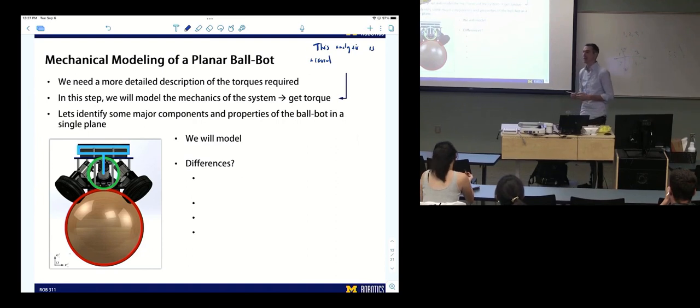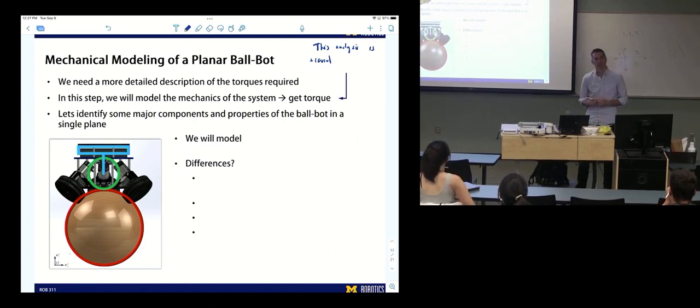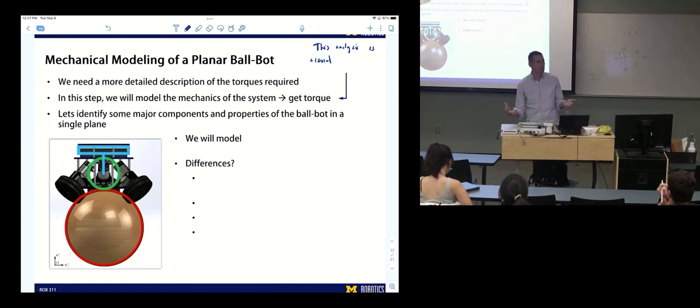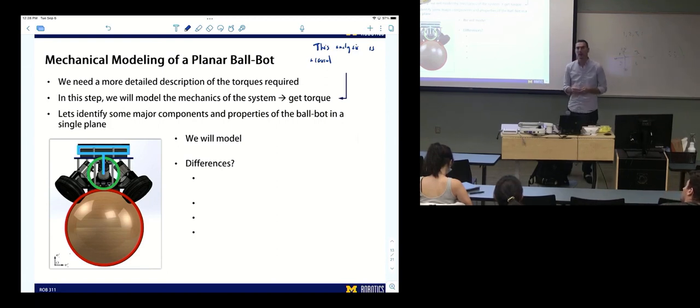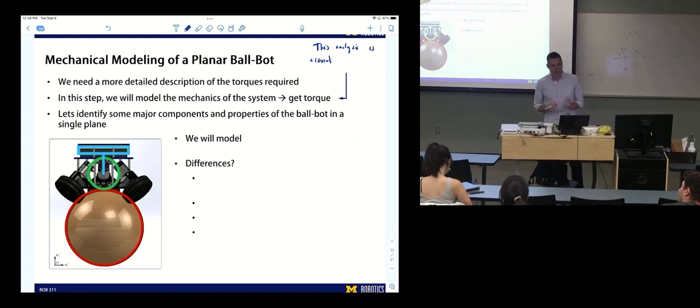We're taking discrete derivatives, which, in this world of high performance computing and really fast sample rates, is an okay way to model, but it isn't the same as forward modeling, which would use something like an ODE solver like Simulink. We actually have the forward version of this, which we can share with you. It's a Simulink model. It's very complicated. It's harder, so that's why we aren't going through that. We're doing the inverse model, and the inverse model is what we typically use to design robots anyways.